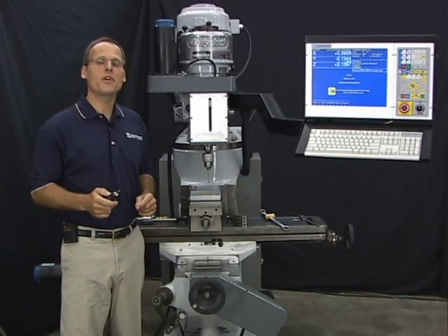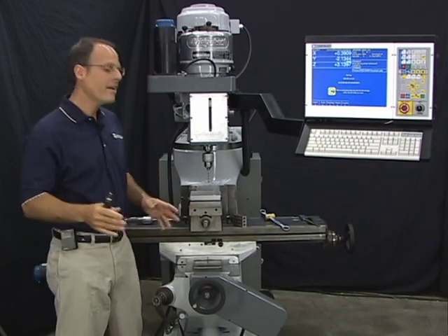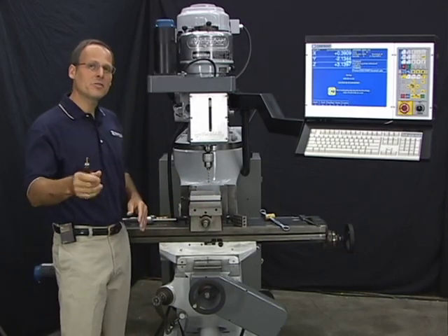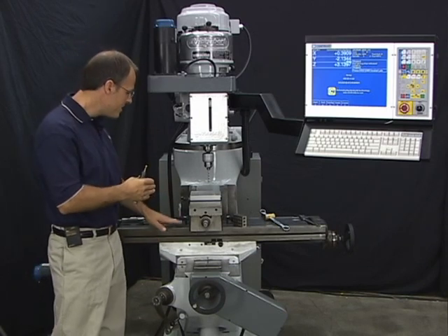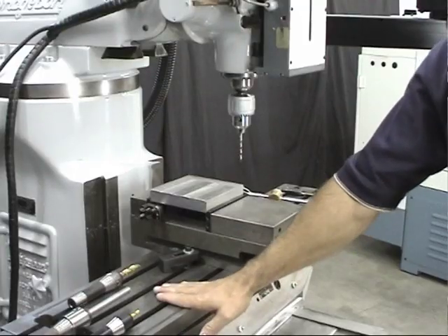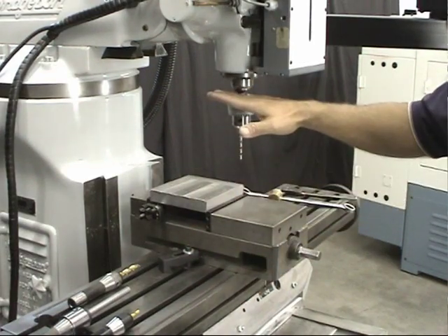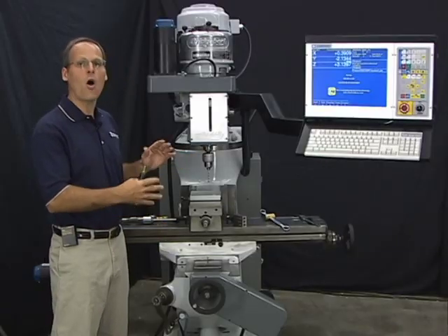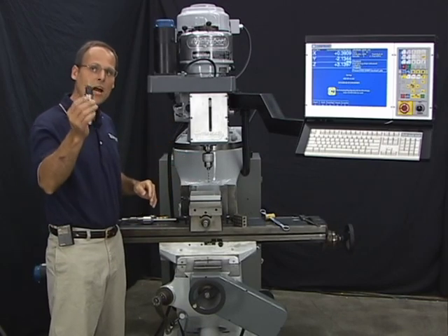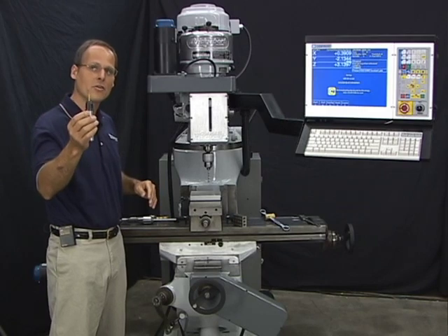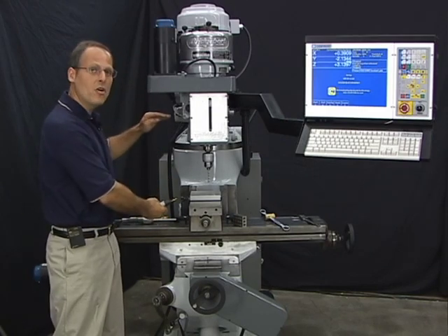Okay, I just got done showing you how easy it is to set the tool heights on a bed mill. Now what about an e-mill? The big difference when it comes to setting the tool heights on an e-mill is the fact that the distance from the top of the table to Z-home on an e-mill is going to change. Now on a bed mill, the distance from the top of the table to Z-home is always the same. It's an absolute. So we use that known distance to come up with a tool height offset value, or the difference in length for each tool, using that known distance.